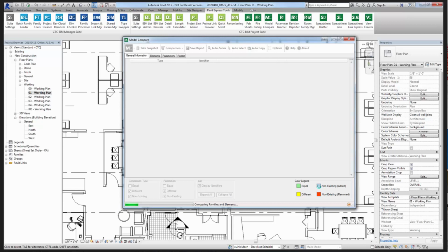Okay. So as it relates to managing revisions, when you want to do things like recalculating quantities, can you get a quantity takeoff out of this tool? Well, not necessarily. This tool isn't really designed for quantity takeoff. It's designed for telling you how objects have changed, not necessarily quantifying exact counts of objects and doing math in certain ways for surface areas and things like that.